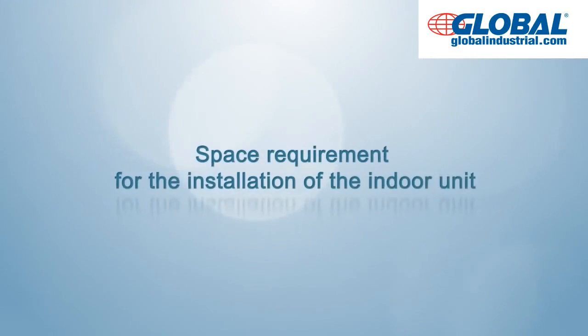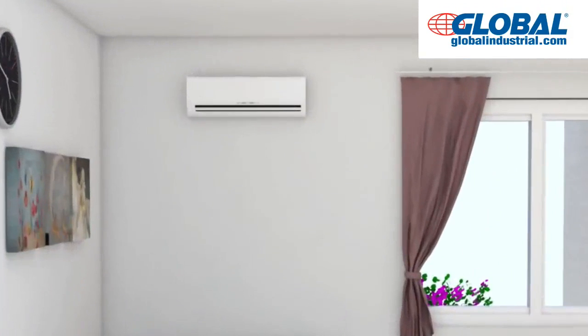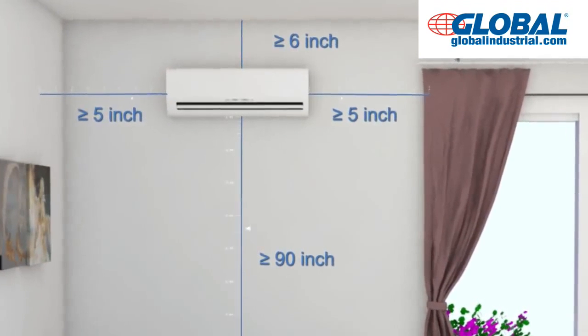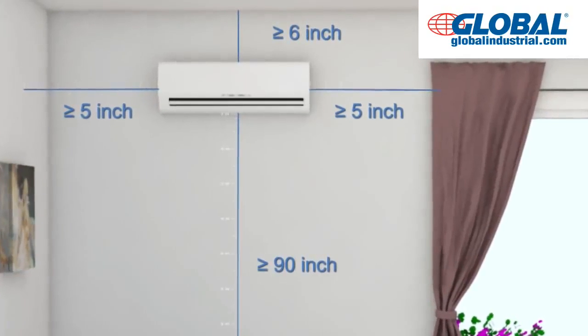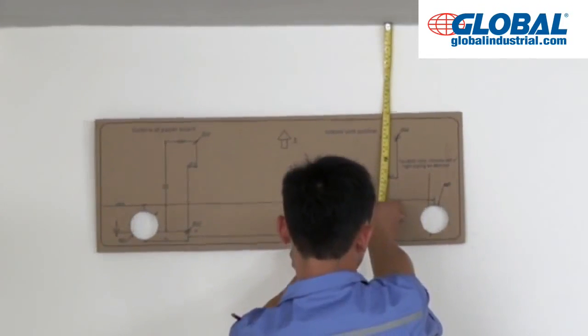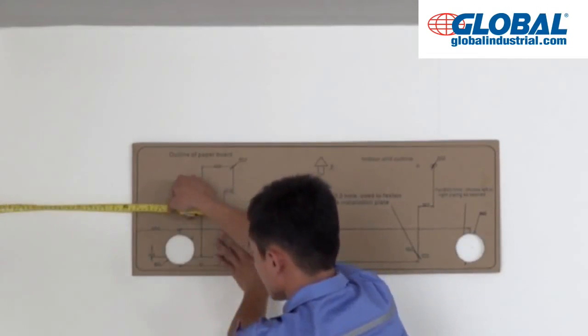Space requirement for the installation of the indoor unit. The right and left sides of the indoor unit should be more than 5 inches away from the wall. The upper side should be more than 6 inches from the ceiling, and the lower side should be more than 90 inches from the ground. Confirm the installation position of the indoor unit according to installation manual.